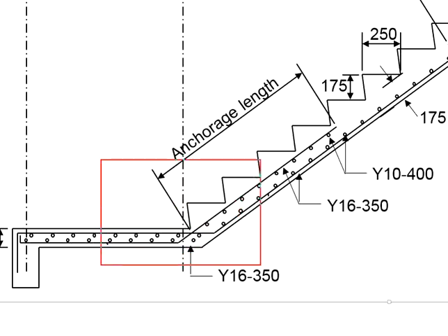Arrange the reinforcement in this manner, where the reinforcement should only bend when it has to, as it is reaching the limit of the concrete edge. We don't simply bend reinforcement bars in the concrete.